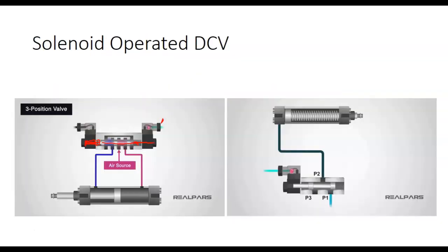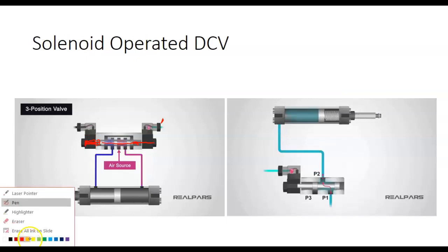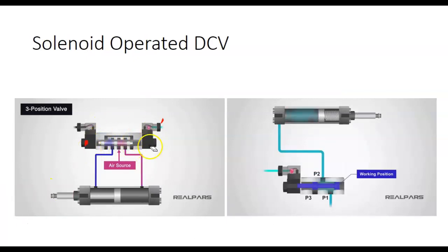And so this would be a 4-port. You can see when it comes in, we block it, then we let it come through. Can you see what I'm talking about? And then we actually control the direction. So a double action cylinder, we're going to have 2 solenoids on it, normally. A single action cylinder, since it vents itself, is normally going to have one solenoid valve. Are we okay? Everybody okay?